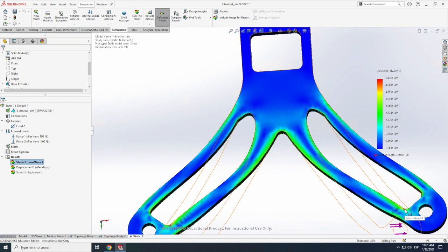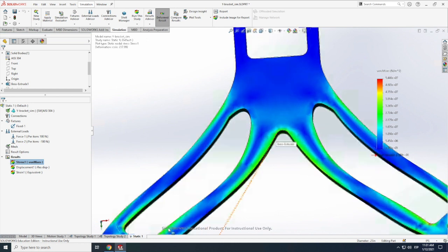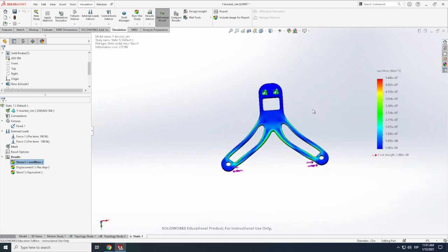Notice also a little bit of red over there, and that's because we have a stress concentration, which generally comes around when we have a sudden change in geometry in our piece, which is something that is essentially occurring when we're using these splines or fillets around here. So we have to be very careful when we're doing that. Nonetheless, we're still well below the yield strength of our piece. We are saving a lot of mass, about 50%. And this is just a good example of how to use topology optimization in Solidworks.